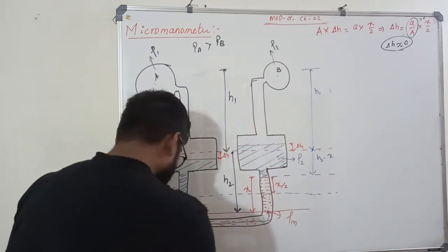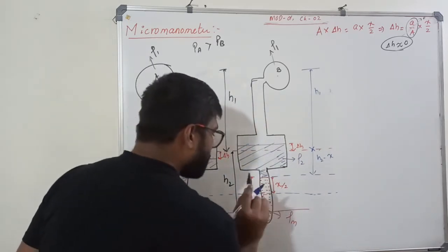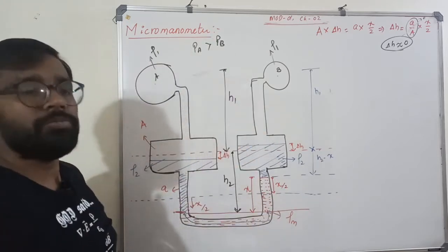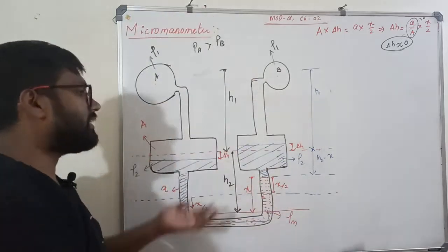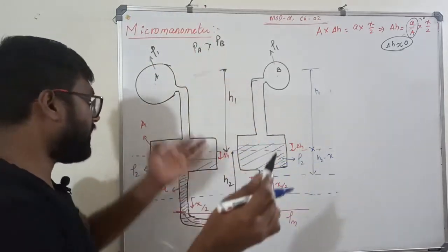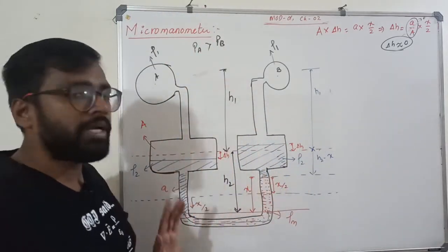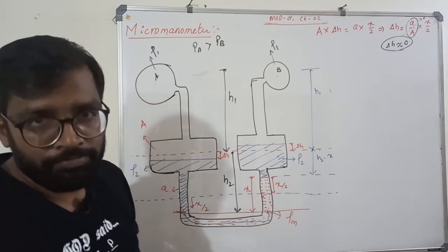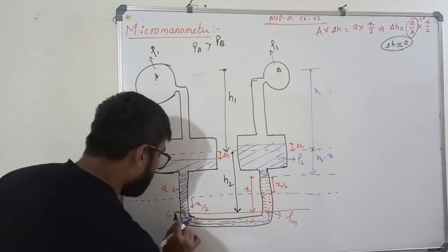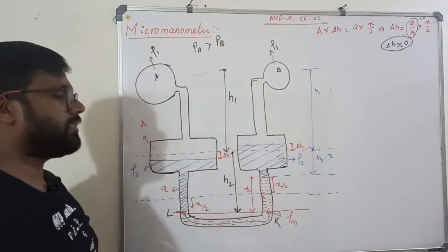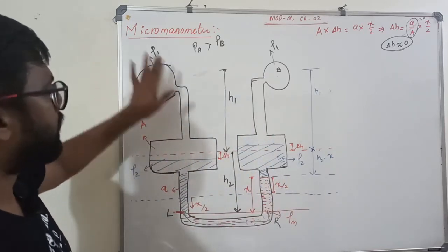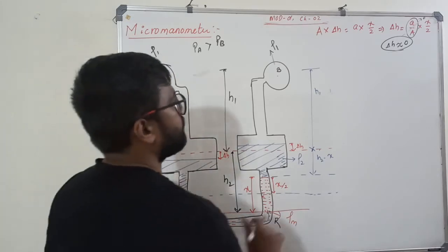So the pressure at A has to be equal to pressure at B. That's why it attained equilibrium. Fluid is at rest. We are studying fluid statics. They did their adjustment, they rearranged, and now this is the final position. No movement, nothing. Hence I can go for Pascal law. So the pressure at left hand limb L and the pressure at this point, right hand limb R, is same. Okay. So now write your gauge equation.